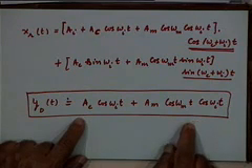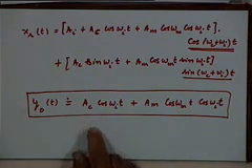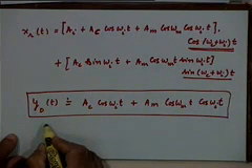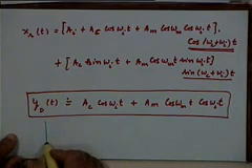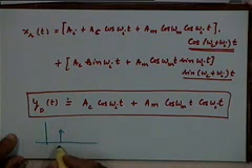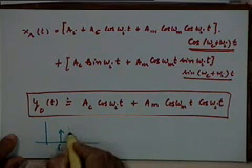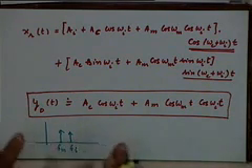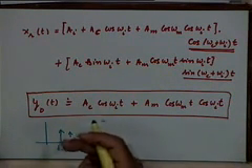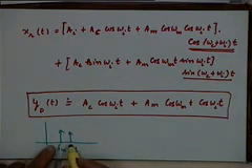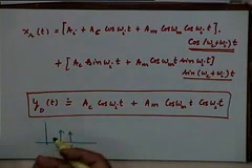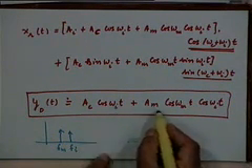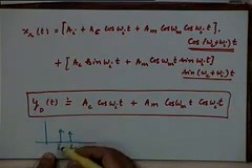That's the second conclusion. Your message signal contained a component at omega m. The input had a message component at frequency f sub m, and there is an interfering component at frequency f sub I. If at the output I got these two components, no problem. That's what the coherent detector does. It produces both these components at the output. Fine, because the input contains interference, the output should contain interference. That's fine. However, what I am getting here is, I don't get f sub m at all.